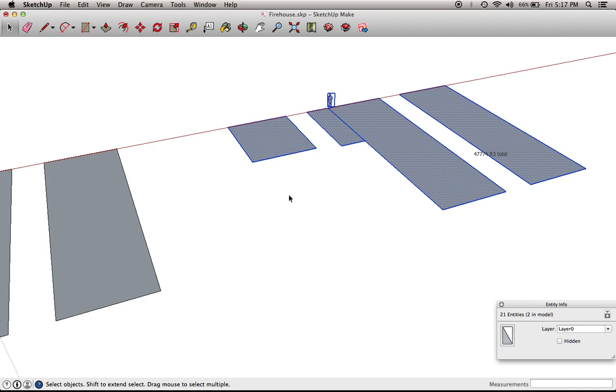Now I'm not going to bore you with the walls because I already showed you how to do that. You hit Command L to draw walls. You go up on the blue axis, let's say 8 feet. I'm still a little clumsy with this thing sometimes. Up 8 feet.